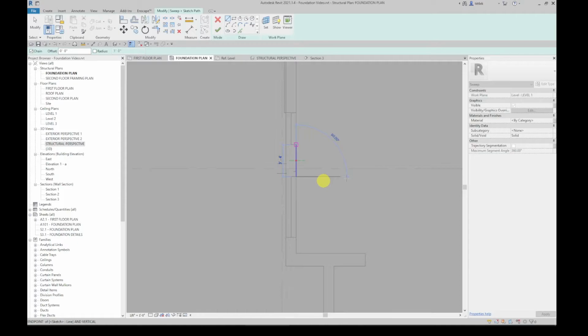And it looks like we did. And let's see, I wasn't sure if I got this right. Yep, that's right on the line. So you can see that between the window wall, and if we go to a generic 3D view, you can see what's happening here is there's less structure, there's less weight in this window wall, so we don't need as heavy of a grade beam as we do where we have all this brick.